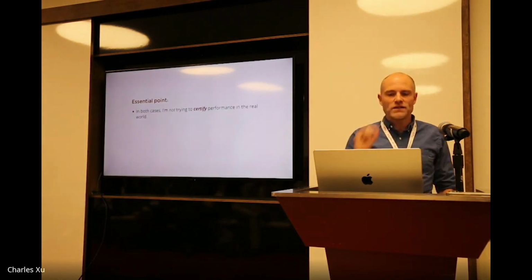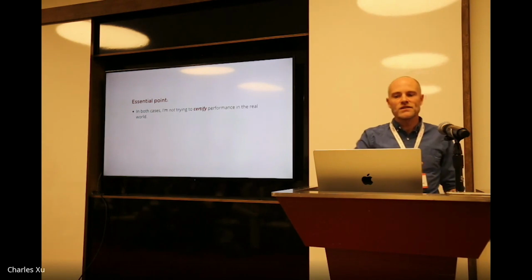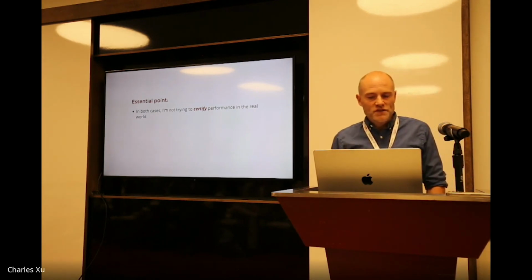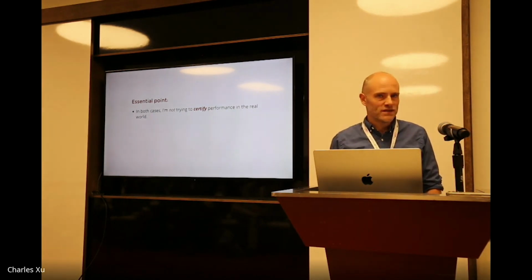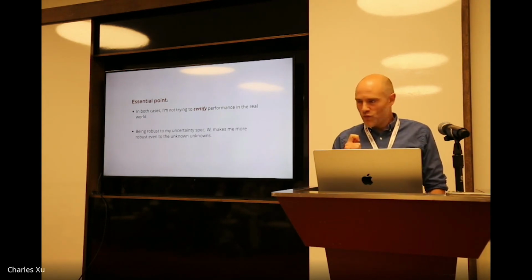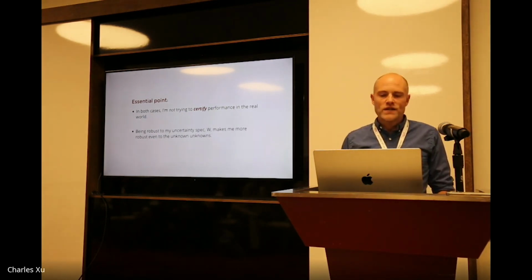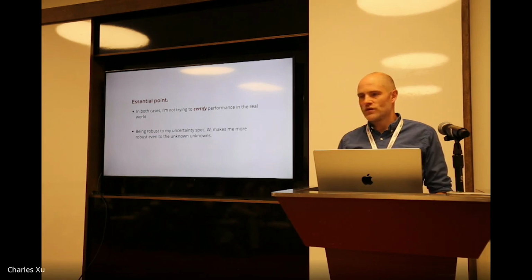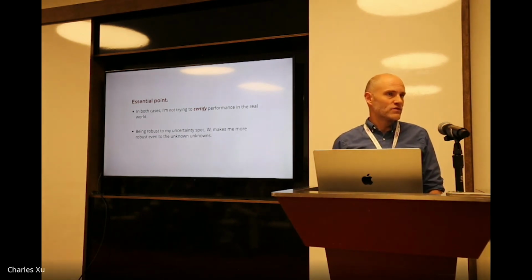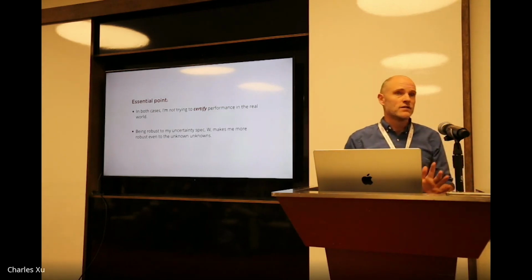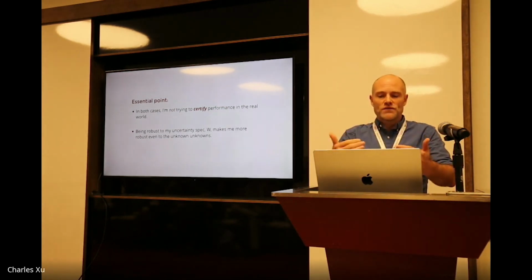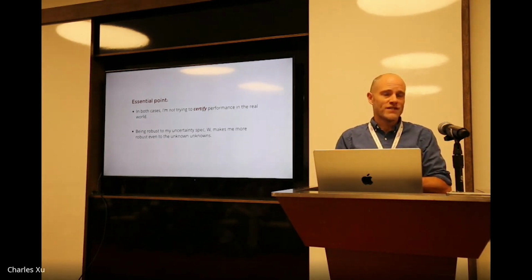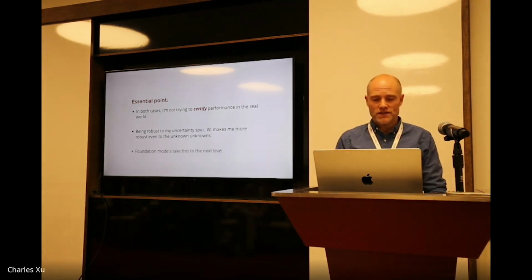Okay, but the essential point is, in both of those cases, in the robust control case or in the stochastic, Monte Carlo stress testing case, we're explicitly not trying to certify the performance in the real world. We're going to pick an uncertainty distribution W, right? Which if I'm trying to be robust to this, then that should make me robust to things in the world, even the unknown unknowns. That's the philosophy that I subscribe to, that synthesizing against a robust objective is good. But I typically stop short of saying I've certified that it's going to work in the real world. That's a long tail to deal with and a very hard statement to make. And I don't know that it's necessary to be successful.